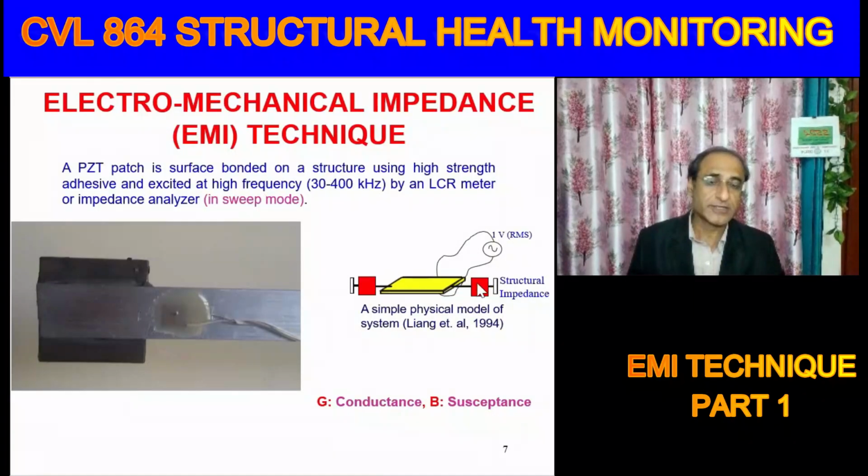the electrical circuit gets indirectly the mechanical properties of the structure, they are reflected in the current flowing through the circuit. So that is now the direct effect. Because the structure is undergoing vibrations, so the stresses will be developed in the structure, and those stresses cause basically the accumulation of the charges and the current flows. So the current that's flowing in the circuit is a reflection of what is inherent in the structure.